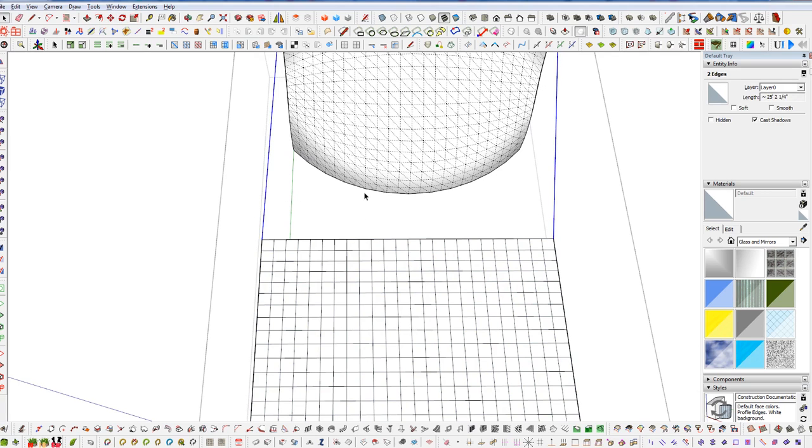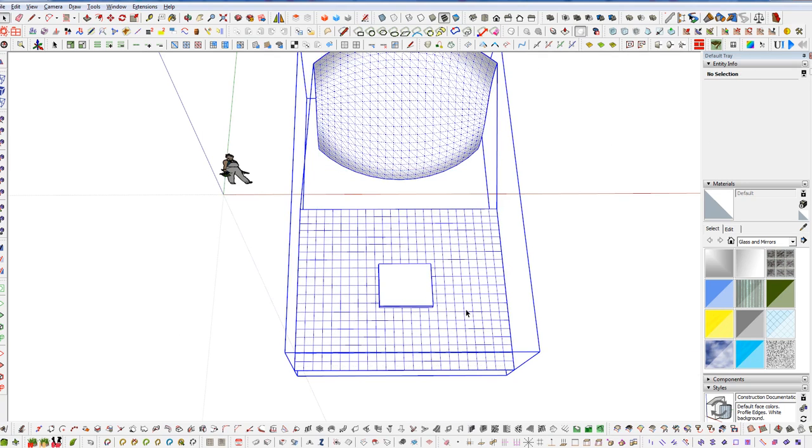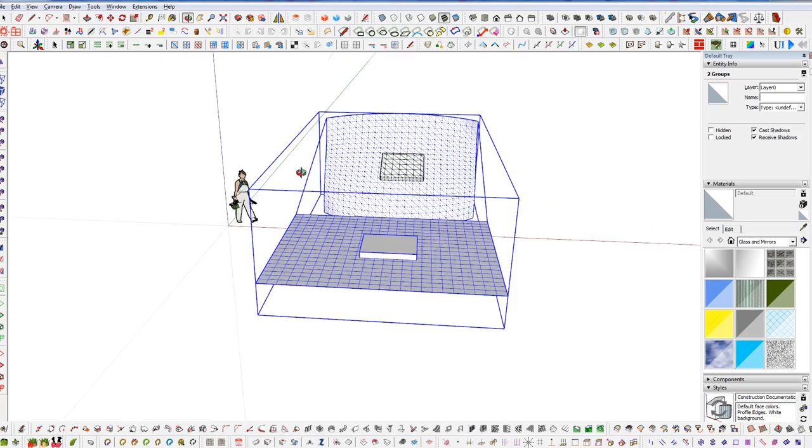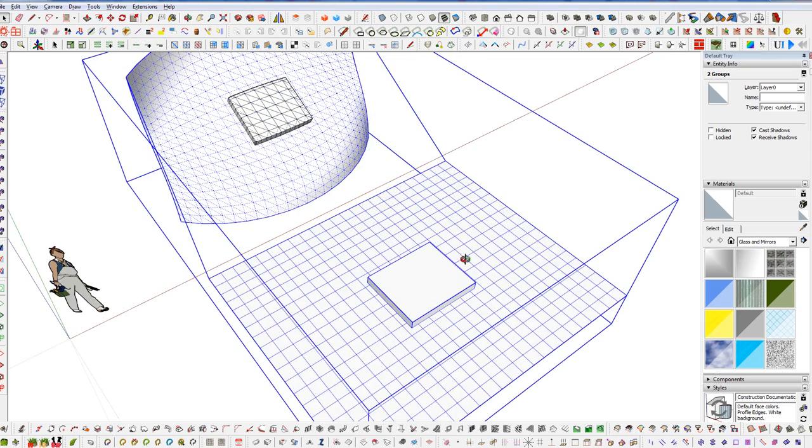Let's try this again, make those into a group, get out, select those, select that, run Flowify, and now it's going to work. So that was the issue. I just had this turned the wrong way there, so we have a different division count in the length and the width, and they need to match up.